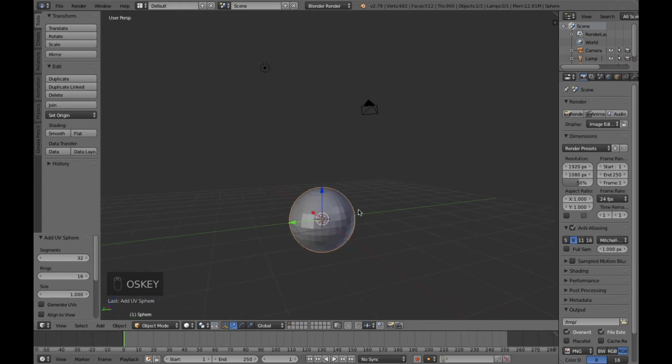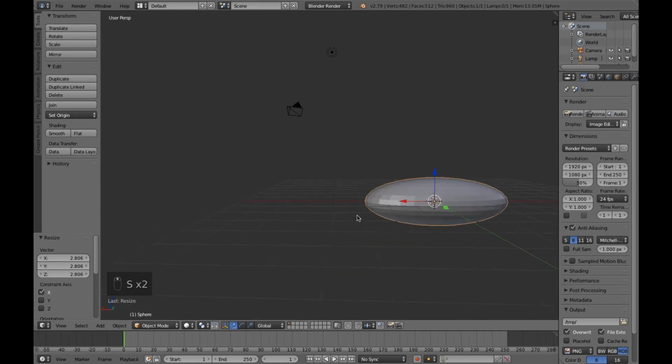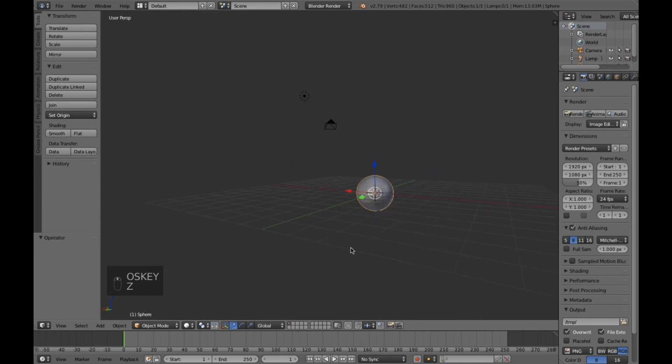Another important thing that I forgot to mention in the video is redo. You can probably do something stupid which you didn't want. You can go Control Z to undo what you did. But let's say you go crazy again and you wanted to redo what you did, and Control Y does not work. So it's important to remember the shortcut for redo, which is Command Shift Z. In Windows, every time I say Command, it's going to be the Control key, which is also something important because you might be working on Windows. So remember, Control Shift Z is redo, Control Z is undo.